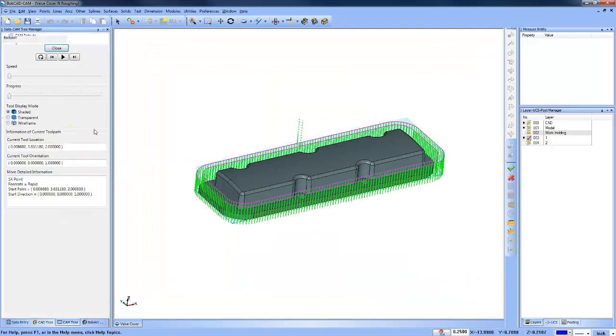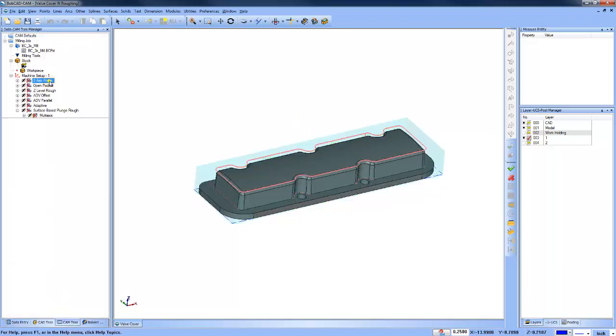I believe that's so that you can back the tool off from the cut so that it doesn't return straight back up. But again, these are just some of the different ways that you can rough in 3D. Again, using a 2-axis profile, using an open pocketing routine, Z-level rough, your advanced rough, or your surface-based toolpaths.